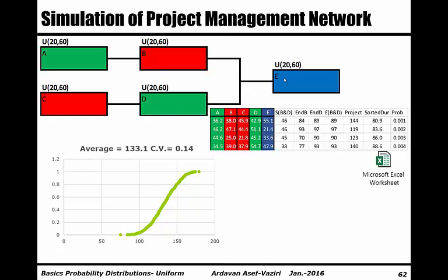We also have resource interdependencies. Both activity A and D need resource green, and we only have 1 green. Both activities B and C need resource red, and we only have 1 red resource. Therefore, technically, activity B cannot start until A is finished, and as far as the resource requirement is concerned, B cannot start unless C is also completed, because B needs the same resource as C.